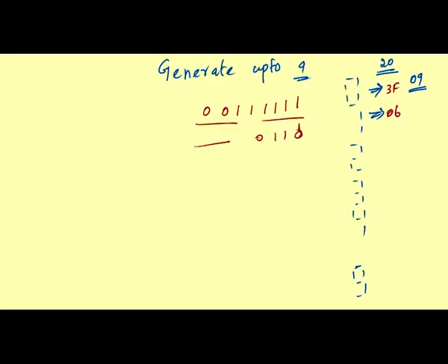So, the same thing: you write A to decimal point, then you write the corresponding ones and zeros, which LEDs are to be on and off. Simply I will give the first one, 0, then the remaining you will continue and do as homework. So, A to F are on, G is 0, decimal point is 0, right.